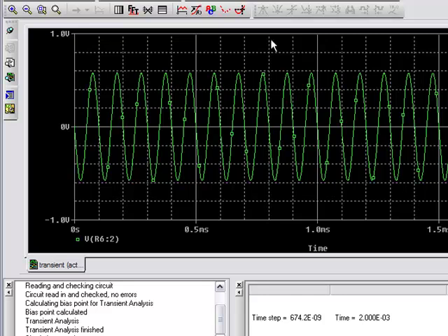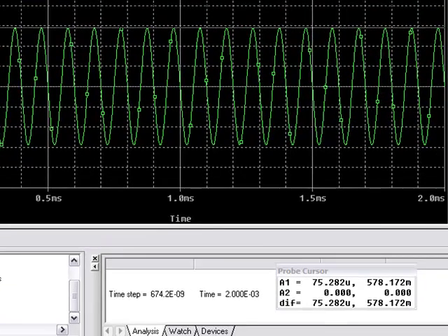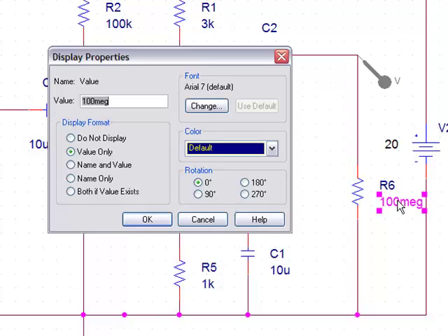Okay, and we'll measure our peak voltage. Right over here, it's around 5.578 volts. So now we need to get the voltage that is half of this voltage by adjusting our load resistor. So basically what we're looking at is around 2.8 volts. So let's go ahead and try to choose our load resistor. Let's put 10K.